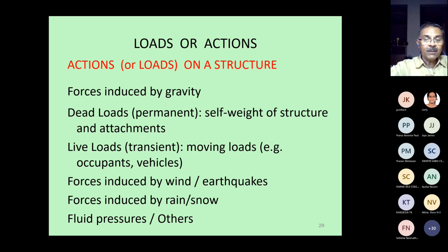where the structure will be vibrated with an acceleration that is contained in the earthquake waves. And the moment we get an acceleration at the base of the structure or the founding area of the structure, this acceleration multiplied by the mass of the structure is generated as the earthquake force or inertia force within the building. This force depends on one property called mass and a second property called acceleration.